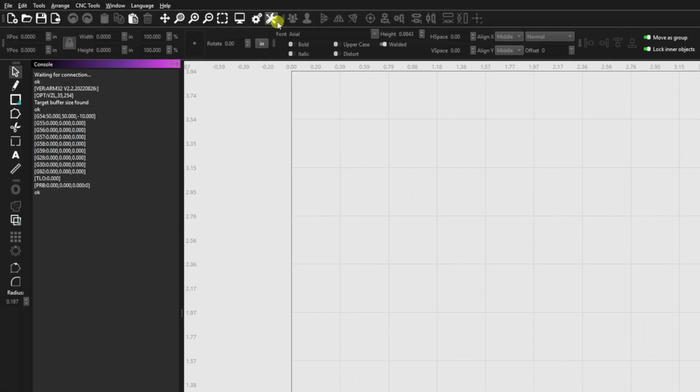So one other thing that is potentially important with this is that if you are familiar with the custom G-code protocol system from Lightburn, that is the only option that is in MillMage. MillMage only supports machines that can take G-code input. Now, that's primarily because that's really all that most CNCs ever use, but also this is just sort of a start, and the vast majority of CNC machines will use this.